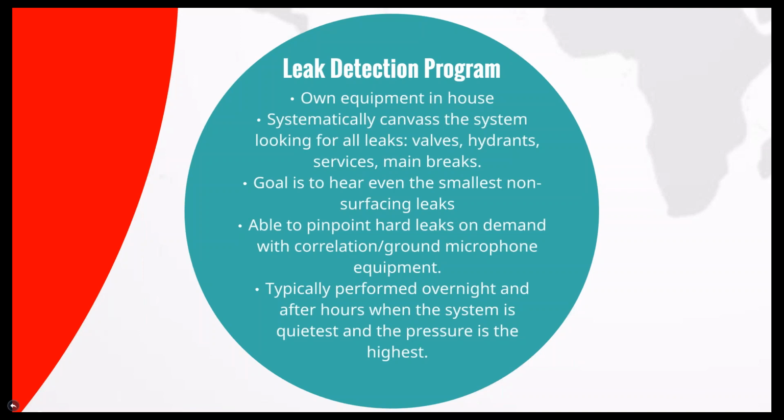Because again, getting some staff and getting management bought in to do these type things is the biggest hurdle, I think, with a leak detection program. So with this type of system, you pick out quarter sections and start using leak detection equipment, whether it's ground sounding equipment, correlators, or loggers. We'll talk about that in a couple slides here, but going through and identifying issues programmatically through your system. And the goal here is to identify non-surfacing leaks.